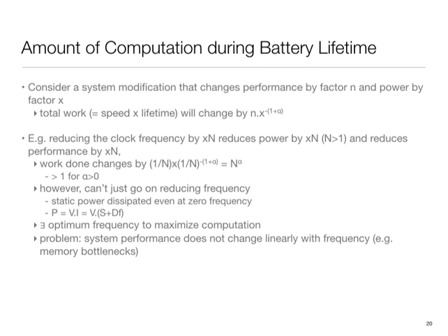If the battery was ideal, alpha would have been 0, and as expected, the work done would have remained the same. But because of this non-ideality, as I reduce the clock frequency, I am actually seeing the work done changing, not remaining constant. In this particular case, I'm increasing the work done by n to the power alpha, with alpha somewhere close to 1, so it's actually increasing.